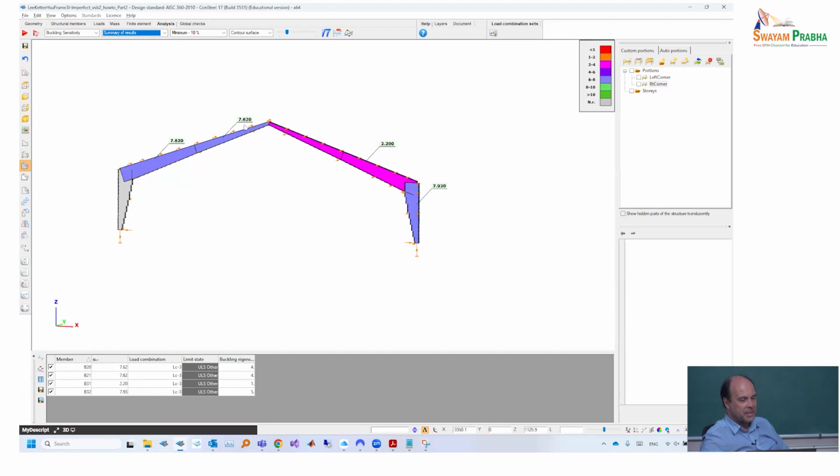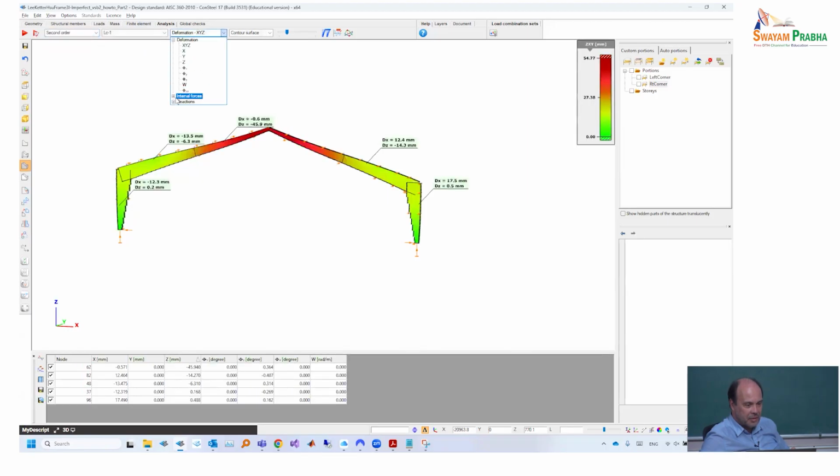Now I already see the envelope of all the modes, and this is still not relevant. Why is it not relevant? Don't forget, we have loads only from left to right. Wind is a very dominant action on the structure, and if there is any wind, that will probably reduce very significantly the force. We can even see how are the internal forces on this column.